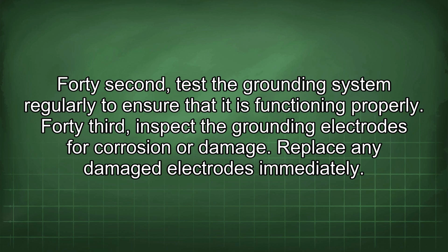42nd, test the grounding system regularly to ensure that it is functioning properly. 43rd, inspect the grounding electrodes for corrosion or damage. Replace any damaged electrodes immediately.